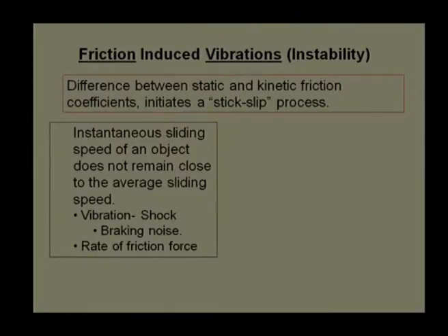That is why noise gets induced when we apply brake. Due to variation in velocity, the wheel is suddenly slipping, and that is why the chirpy noise comes, which is many times intolerable. That is why when we design good brakes, we try to keep this in mind. This kind of noise should not be there, or if it is there, it should be at a very, very low level. We try to design brake and brake material from that angle, so that minimum noise is generated when we are applying brake, when we are trying to stop the vehicle or the wheel.